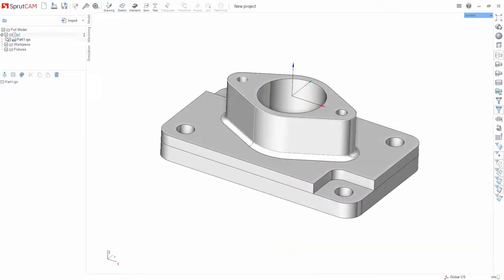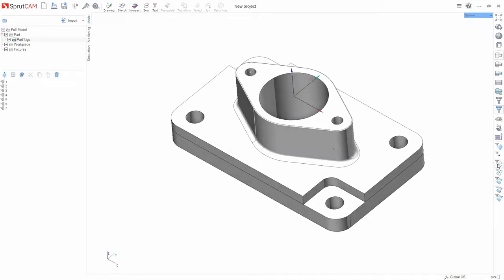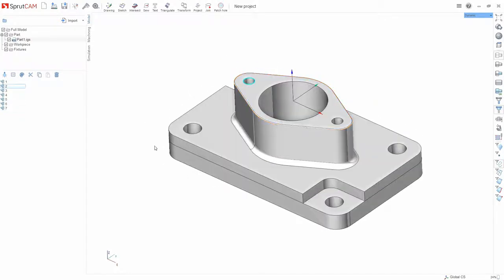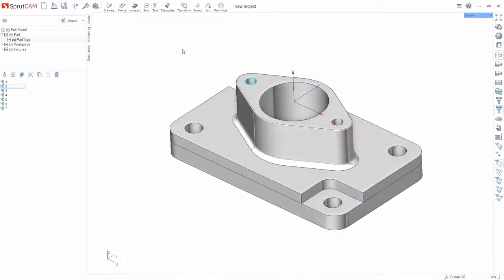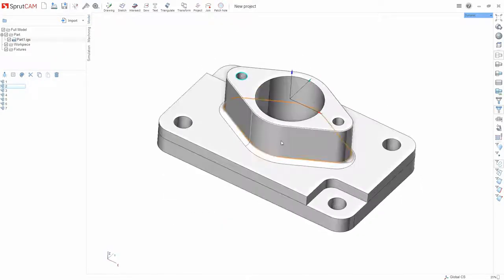If we select the catalog with elements of the part in the tree, we can see from which elements the part consists of. Here we have points and curves, as well as separate surfaces. Here we can use the filter that we watched in the first part of this video. For example, if we enable the ability to select only curves, you can select separate curves. These curves are located in the model, which means they were created by the designer in the process of designing this part.